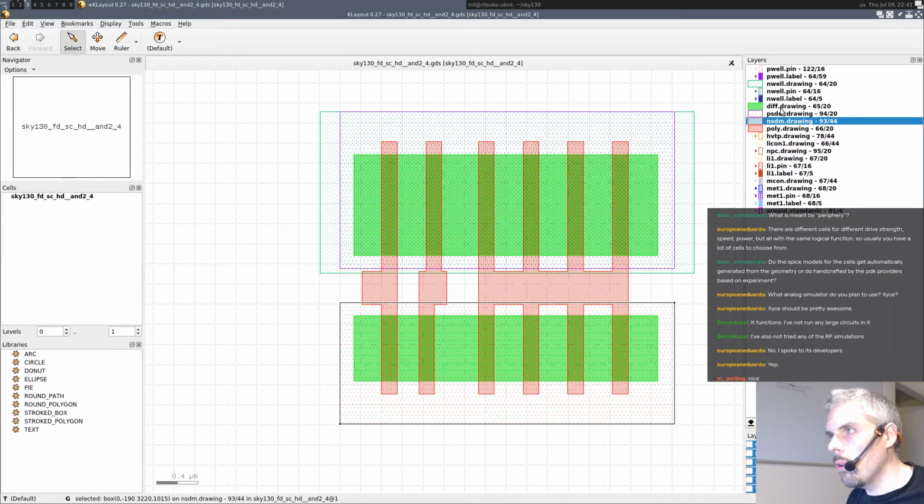I think the first step is basically to create an opening for the active region in the field oxide, and then actually proceed to the implantation. Those are the two different steps of the process, and these will represent the actual masks that are going to be used.